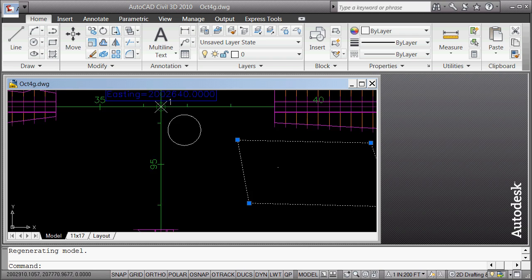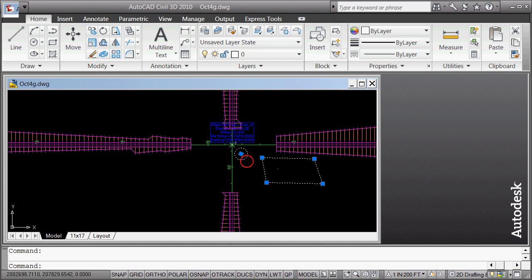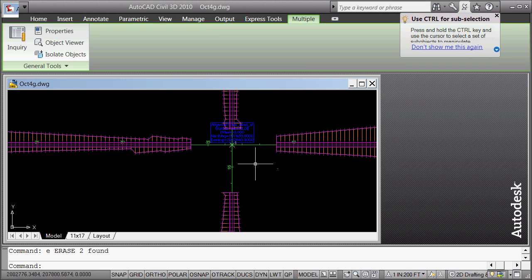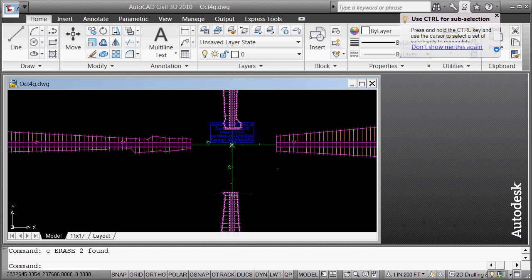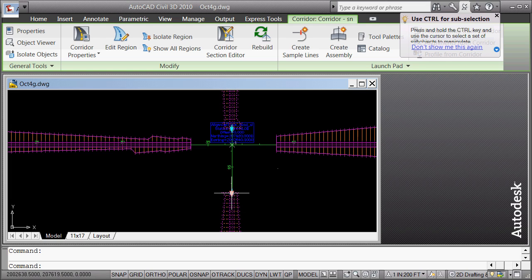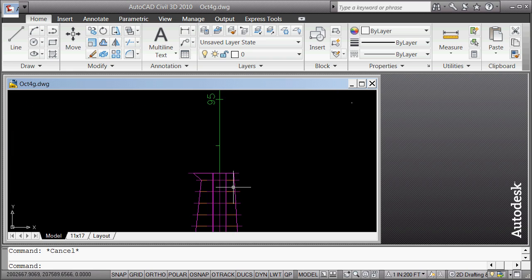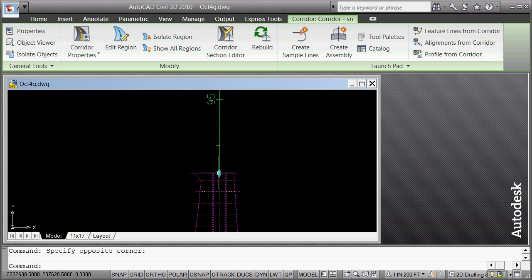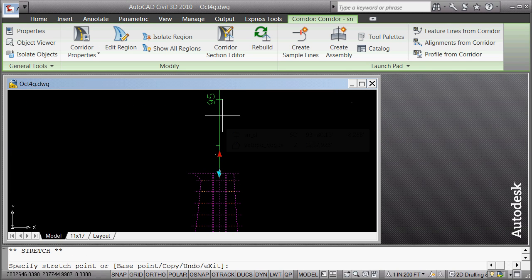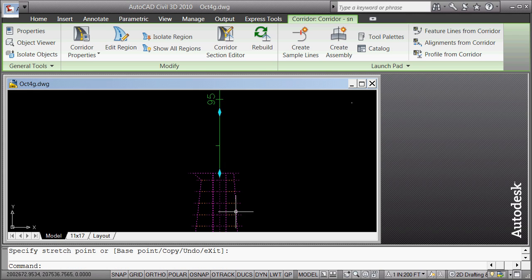So you start to see just a real bad basic review of why we start to use grip snaps. Here in this case I show it to you because you can change your corridor just by grabbing and pulling the grip snap on the corridor eventually. You can click on this and shift the two of them. You've got to shift two ends, and you'll be able to shift the corridor using those grip snaps. Not doing a great job there, but I'll still put it.